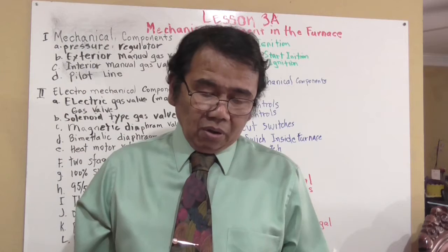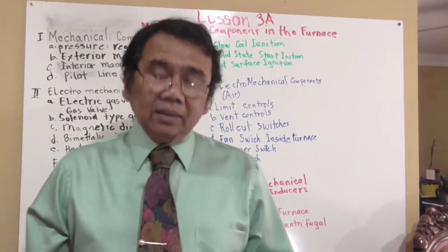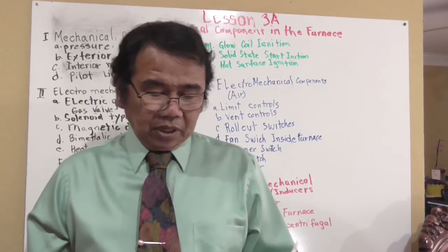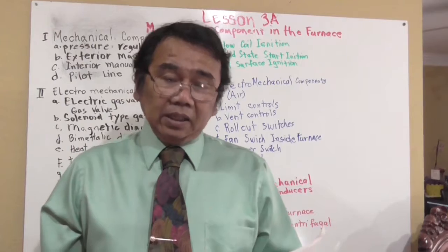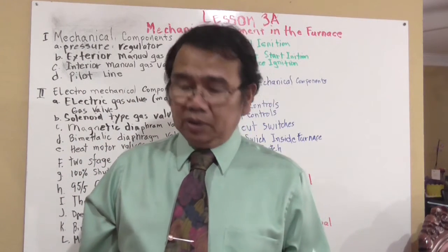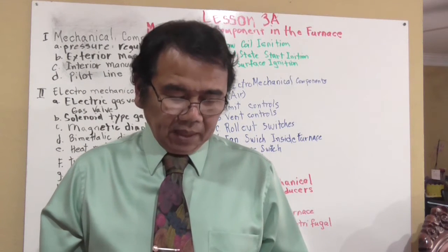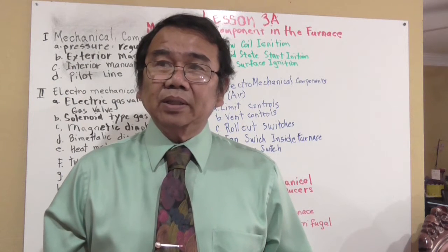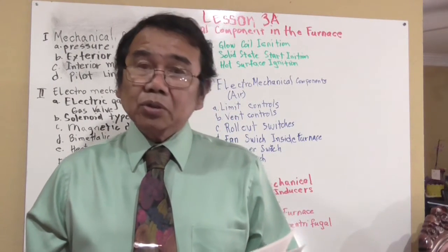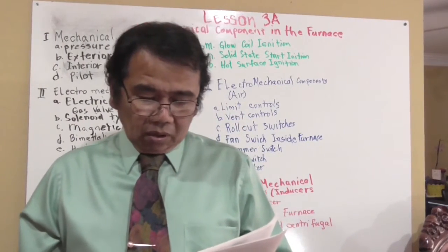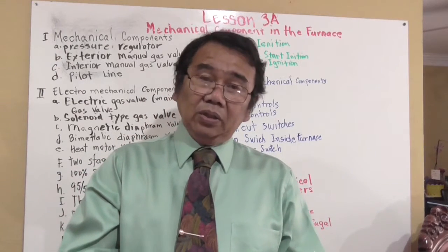Several types: we have temperature on, temperature off; time on and temperature off; and time on and time off. Adjustment can be made for different duct conditions. Delay on time to reduce circulation of cold air in the plenum, not usually above 150 degrees Fahrenheit. If you exceed this temperature, then the limit switch will stop the fan and stop everything, because you don't want any overheat inside the furnace. Delay off time for increased efficiency, not usually below 90 degrees Fahrenheit. Not all models have both adjustments. Read the manufacturer's information sheet when installing a new switch.